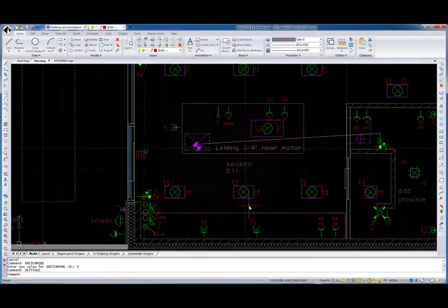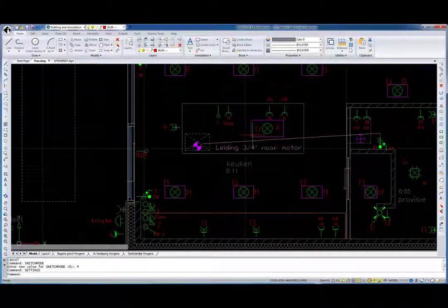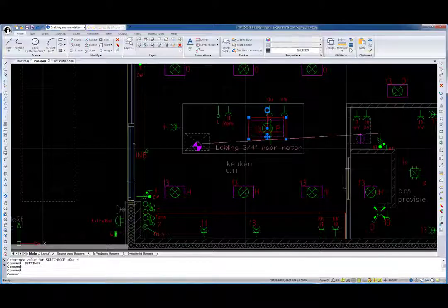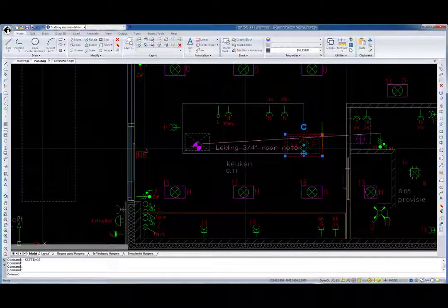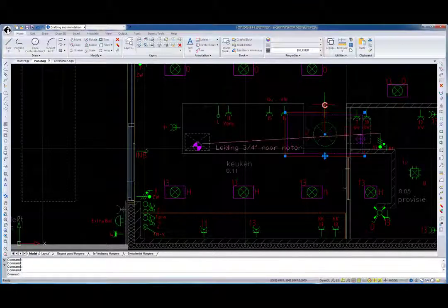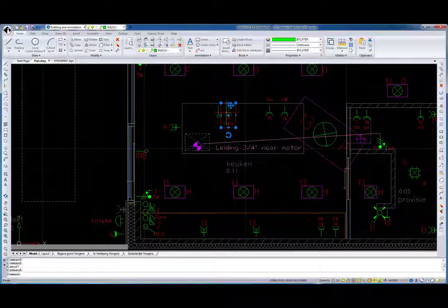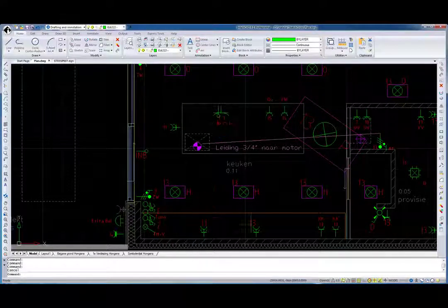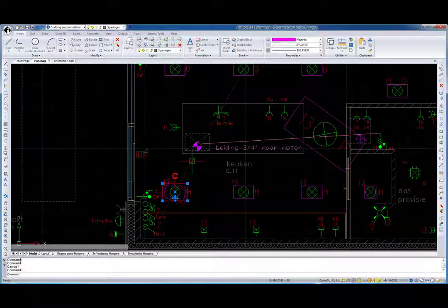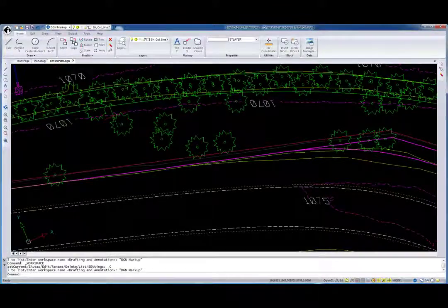So now we can select an entity or group of entities and review selection grips. In addition to the entity grips, there is a bounding box shown in dashed lines around the selected entities. Selection grips can move, uniformly scale, and rotate the selection in the bounding box. Non-uniform scaling is available for single and multiple blocks. You can use polar tracking for selection grips. Just specify the polar angle increment and rotate an entity to see how it works. Also, selection grips are available in DGN mode.